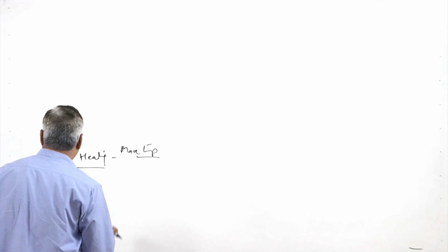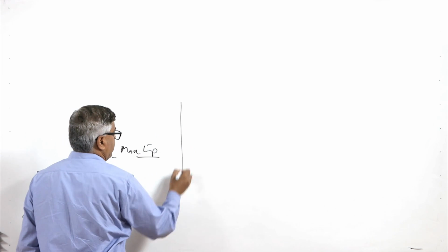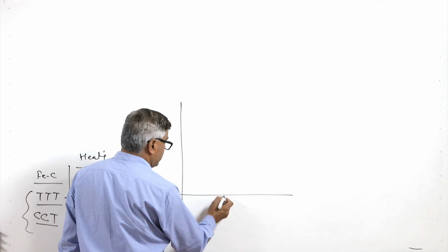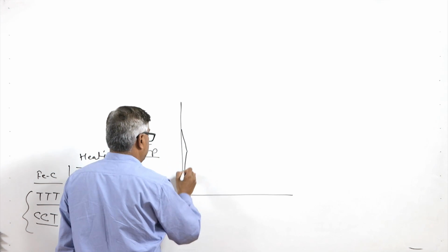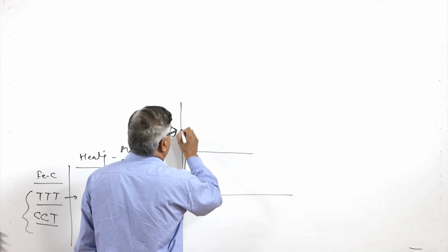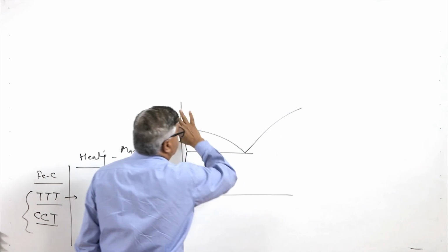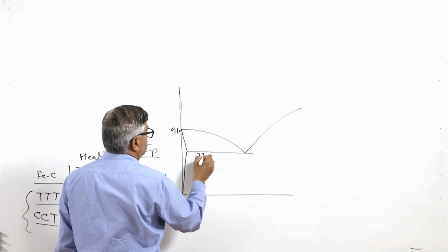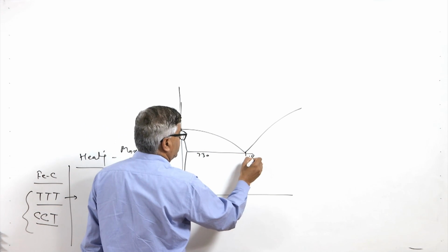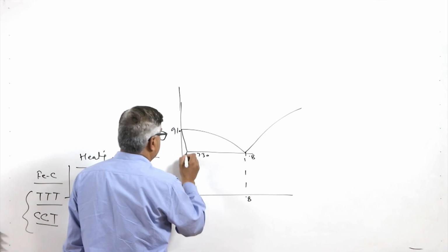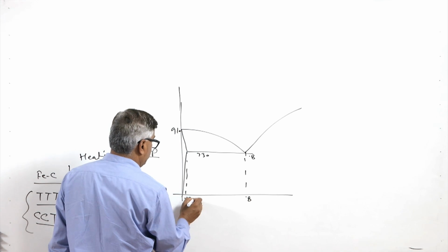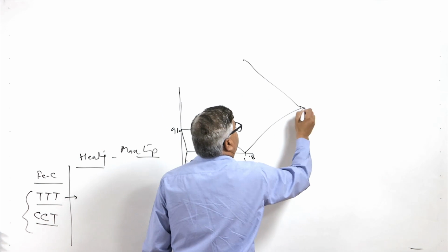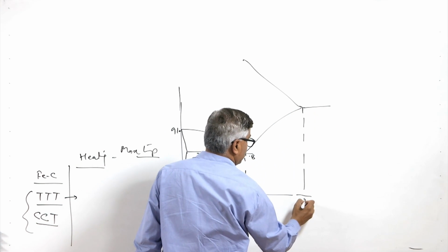We will talk about the iron carbon diagram first. It is like this, wherein this is the zone of interest for us. It is 910 degrees centigrade, it is 730 degrees centigrade, this is corresponding to 0.8%, and this is very less, it is 0.025%, and here it goes in like this, although this is not of interest for the steels, but this occurs at about 2%.